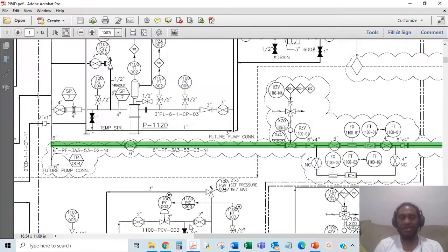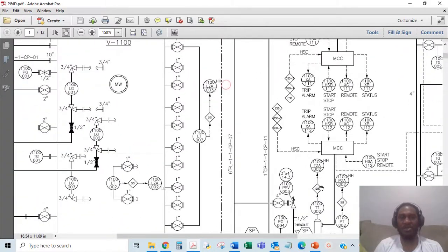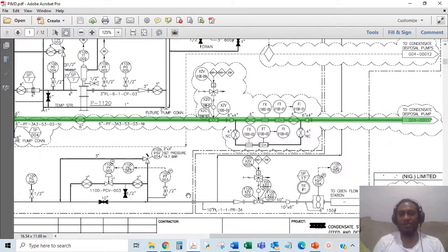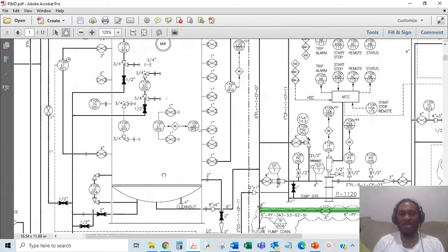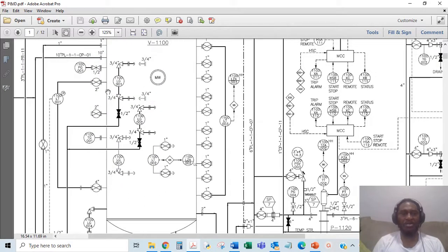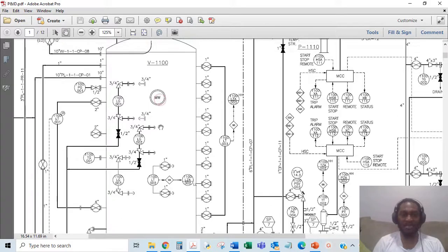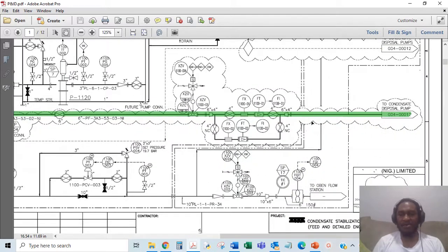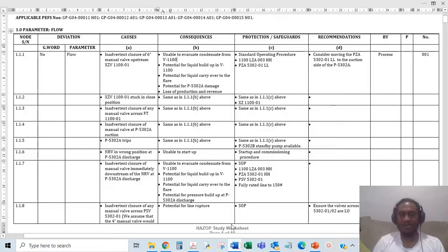That's this. And the same thing, the safeguards, those are the same safeguards that would pick it up when there's a problem. The trip on here, and that's the high trip, and the low trip further down the line. Also, there should be a level high alarm somewhere here. There's also a gauge. All of this is local. You have to actually go to the vessel and look at this, but there are different things that should alert you when there's a problem there. Then going further down the line, so you said same as above, and then yeah, those are the safeguards.